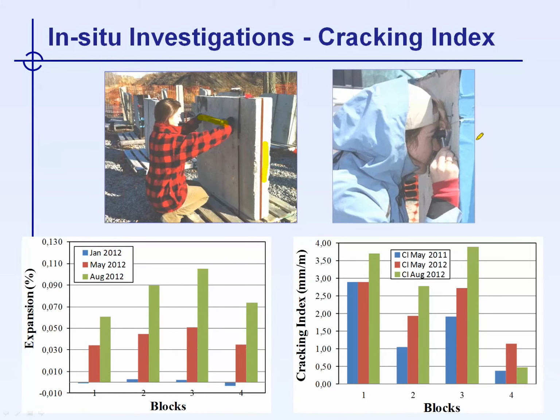And so the lady here is measuring the expansion and the cracking index on this face of the concrete wall. And as you can see here, for this plot, you have the percentage of expansion as a function of time over a 1-year period using this measuring device here.